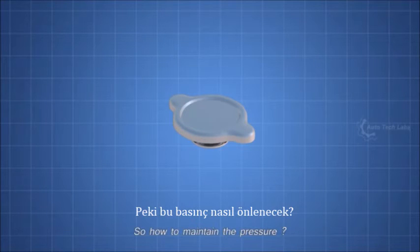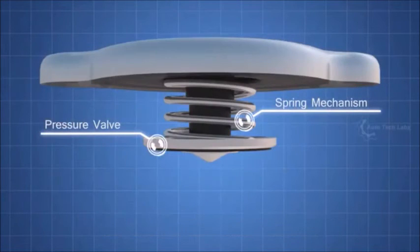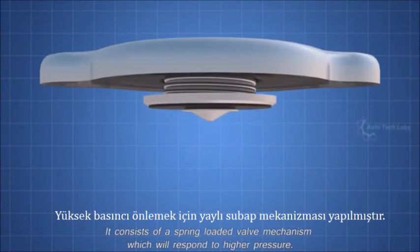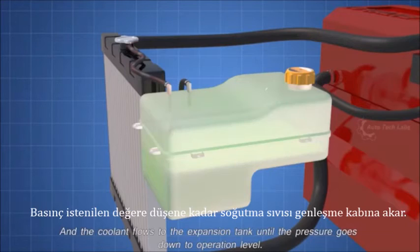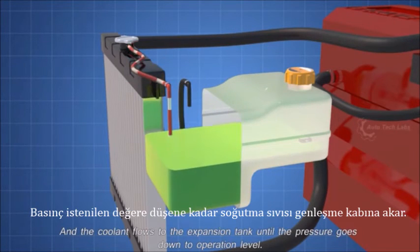So, how to maintain the pressure? Here comes the role of the radiator pressure cap. It consists of a spring-loaded valve mechanism, which will respond to higher pressure. Reaching a pressure above 15 psi will push the pressure cap valve, and the coolant flows to the expansion tank, until the pressure goes down to operating level.